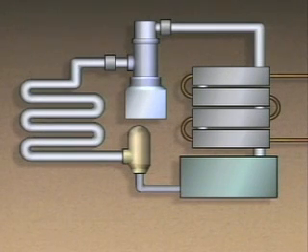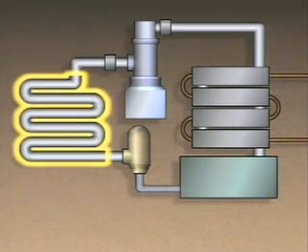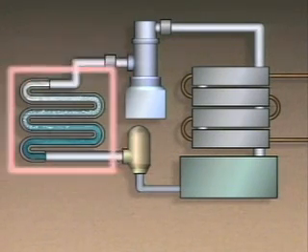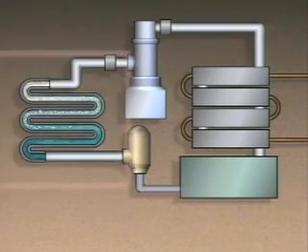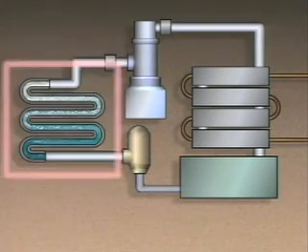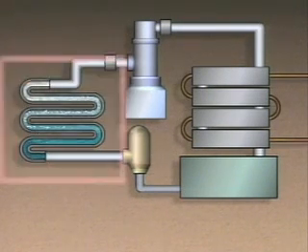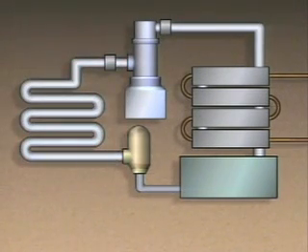In a vapor compression refrigeration cycle, the component in which the refrigerant absorbs heat is an evaporator. In the evaporator, the refrigerant evaporates or boils into a vapor. At the same time, the area around the evaporator is cooled. The evaporator draws heat from its immediate surroundings. This heat is transferred to the refrigerant because the temperature of the refrigerant is lower than the temperature of the evaporator's surroundings. To move the refrigerant through the cycle, energy must be added to it.